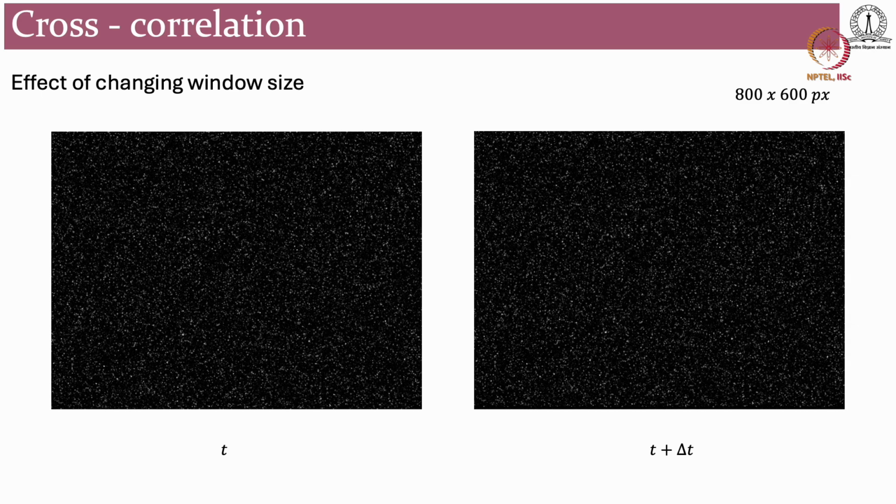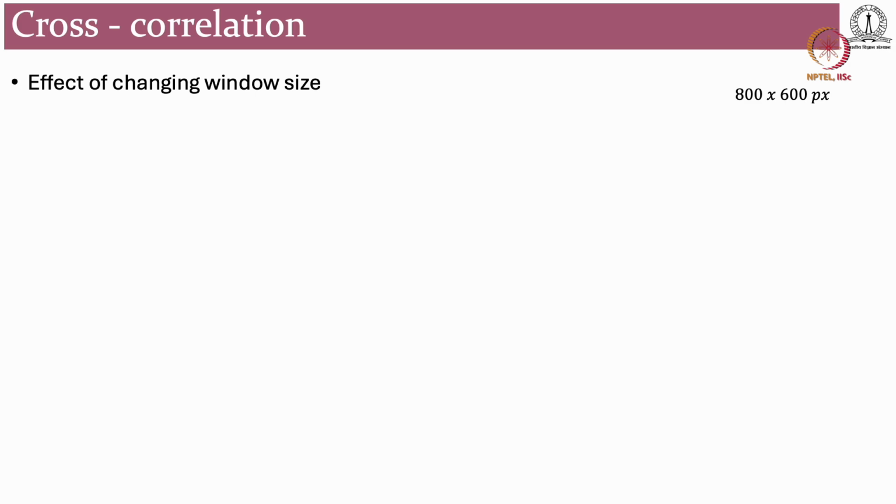This is very well lit, and you can see the particles very clearly, and as you can see, it is very densely packed, unlike in the case of PTV where the particles normally have to be sparsely packed to track them, right? And just by looking at it you won't be able to see the difference, because the delta t is very small, but if you play it in a loop, you can see the particles shifting. That can be done. But now I'll show you what we do.